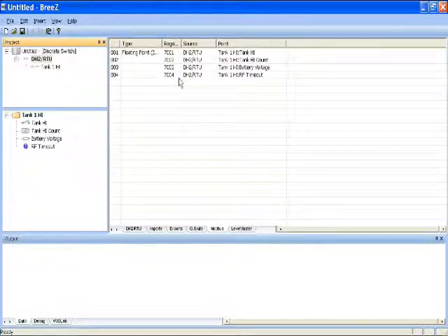7001 through 7004. You see tank high, the tank high count, battery voltage, and RF timeout. This is your Modbus list. This is what you will build your request block from your Modbus master to ask for.